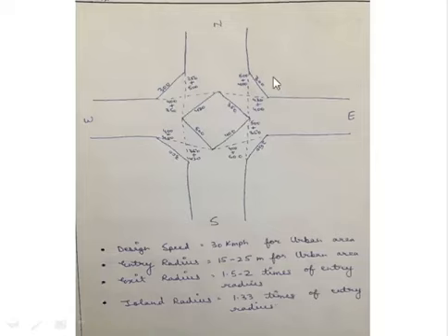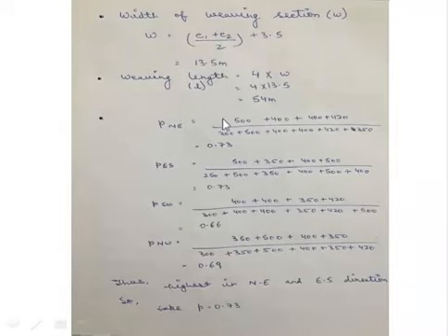So the proportion of viewing traffic will be 500 plus 400 plus 420 plus 400 divided by 300 plus 500 plus 400 plus 420 plus 400 plus 350. This will give us the proportion of viewing traffic in northeast direction. Similarly, we will calculate this for east-south, southwest as well as northward direction. The highest proportion will be taken as the value of P, which is coming out to be 0.73.